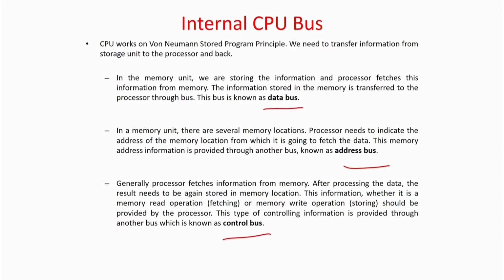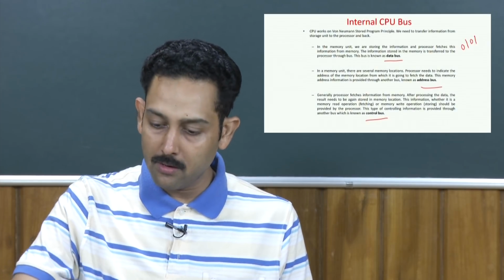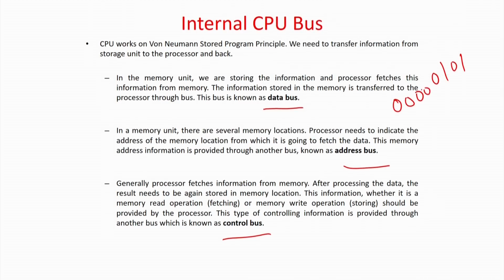It will take the number, say 5, that is maybe 0101, from register 1 and transmit the data to register B. In fact it's an 8-bit bus, so the 4 LSBs will be 0. So the bus which will be doing this is actually called the data bus.